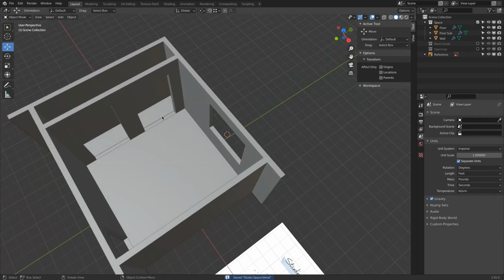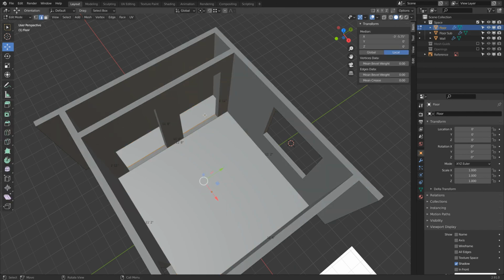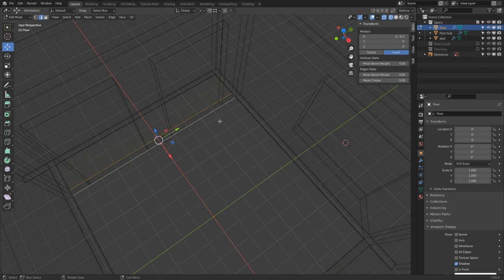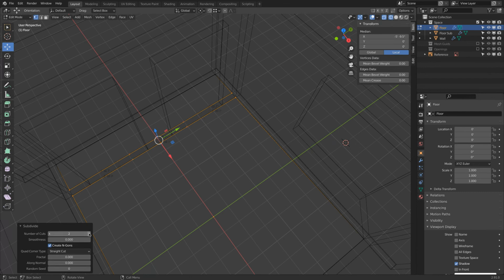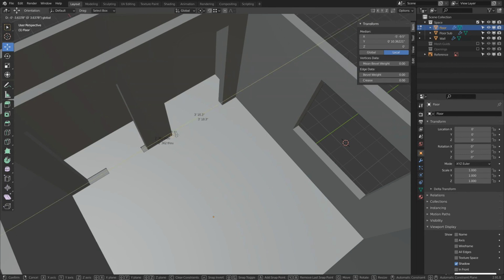The only thing left is actually our floor. So here we select our floor object, not the subfloor. Go into edit mode. Select these 2 edges, so this one and this one. Right click, subdivide. Hold on. Actually, undo. Maybe showing the points will be easier. Point select, so right click, subdivide. So now we have 1 opening, 2 openings. Okay, good. So we select and press F. You see how it fills the space. F, and then these 2 points here, select, move and snap.